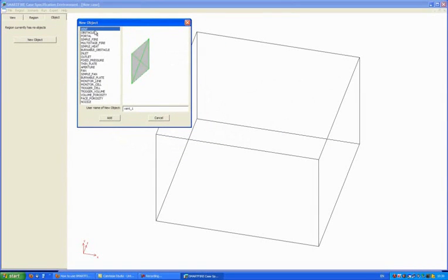The current list contains vents, which are openings in the outside of the structure, obstacles, which are solid materials which prevent flow, portals are objects which punch holes through obstacles, such as a door portal. Simple fire, multi-stage fire and simple heat are locations of fires with different properties to allow a heat release rate or fuel depending on the type of model being run.